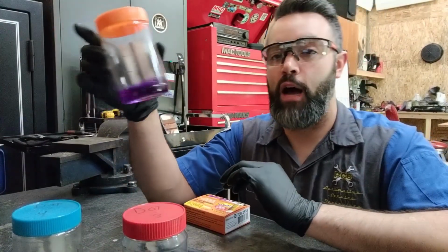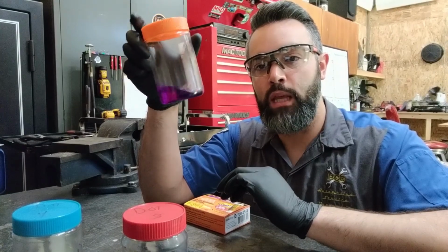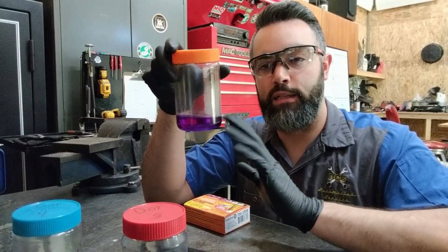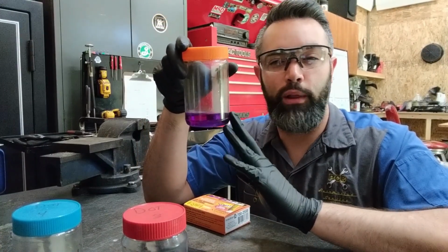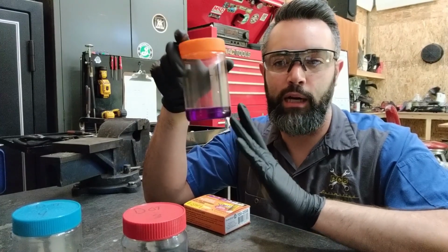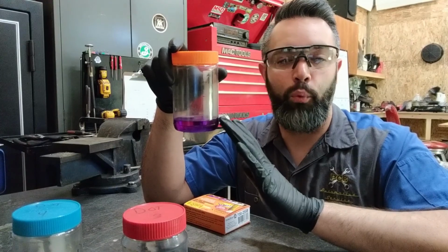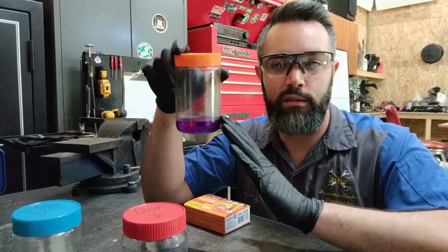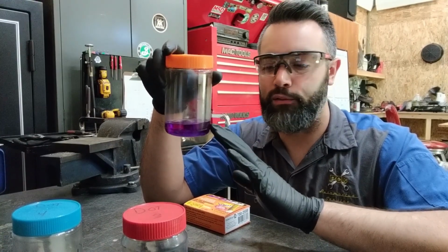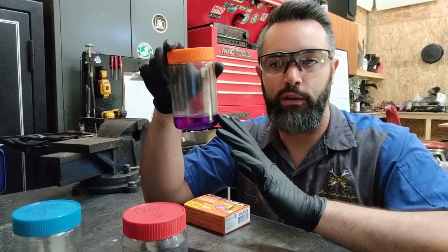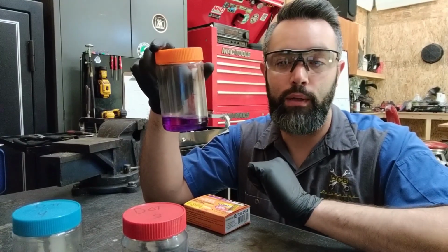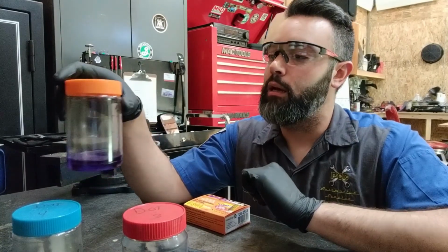Other applications for DOT 5 brake fluid. Since this is a silicone base, it does not absorb moisture. So boiling points for this one are hypothetical. There is a vaporization point for this fluid, but the wet specification is essentially made up because water will not mix with silicone or mineral oil brake fluids.